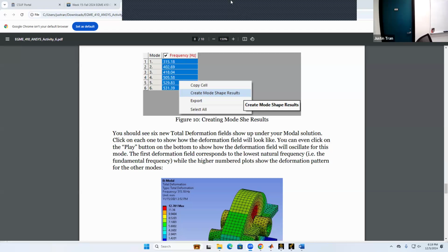At the same rate, all the components of a line for one. Well, if you can find an assembly that has all of them, then you just simulate that assembly, and you can look at the stresses and deformations of each part, individually breaking them down into the different stresses they experience. Yeah. So that's definitely one way. From that situation, you can say which of these components are the most likely to fail.